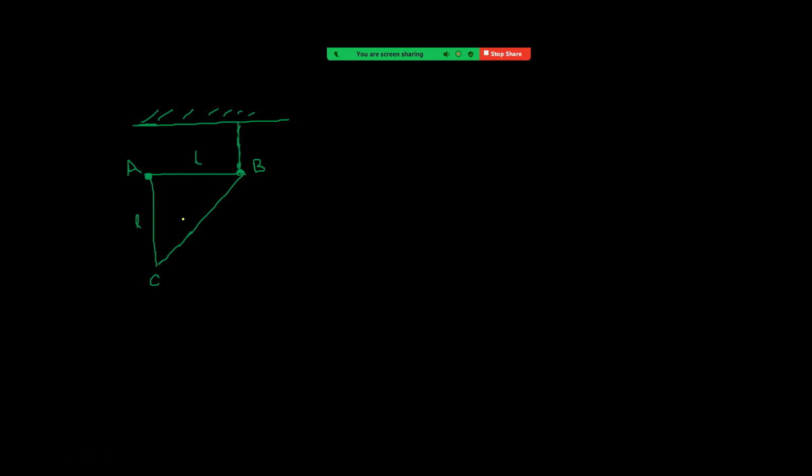So first focus on a free body diagram. So here tension T upwards, and here mg which is through the centroid, right? Mg downwards, and here that reaction force. So take it as F. That F we have to calculate. Okay. So what we can do is, let us calculate tension by taking the torque equation.